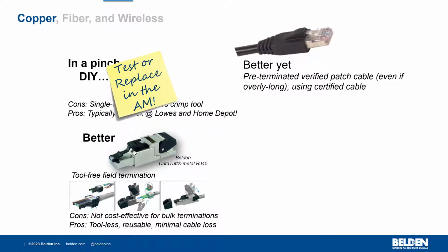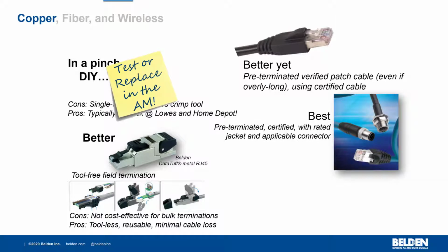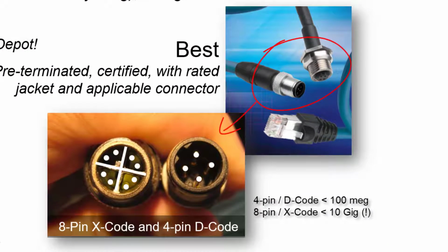Better yet, opt for pre-terminated verified patch cables, even if an overly long patch cable, and ensure that if you're going to terminate or re-terminate any ends, that it is a certified cable. And the best possible solution is to use a pre-terminated, certified, and rated jacket and applicable connector, be it an RJ45 or an M12 Ethernet connector, which we see here.